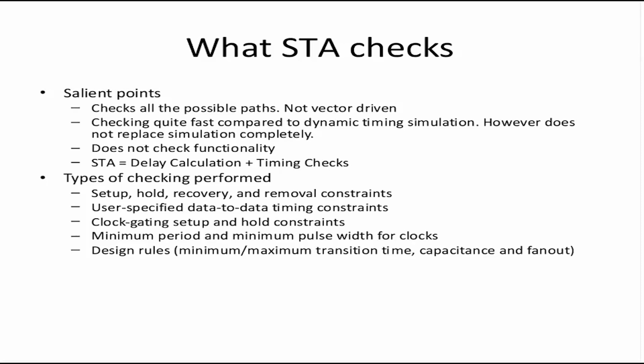It does not replace simulation. The important fact is it only checks timing. It is not a functionality check. How do you check functionality? By doing verification plus formal verification. So STA does not replace functional verification. STA is comprised of majorly two parts. First part is delay calculation, second part is timing. That means first delays are calculated, then they are checked against the constraints.